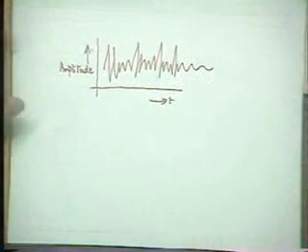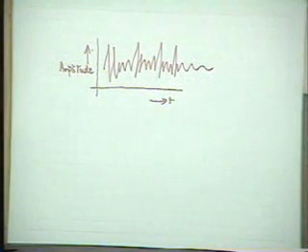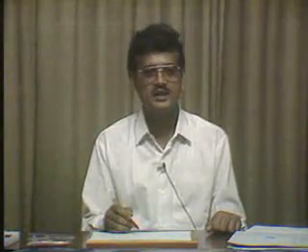If the signal is something like this with respect to time, what we really have is very sharp, quick transitions in this signal, and if we do the Fourier analysis of this signal, we will find that these kinds of signals are rich in high frequency components as compared to maybe some kind of signal like this.